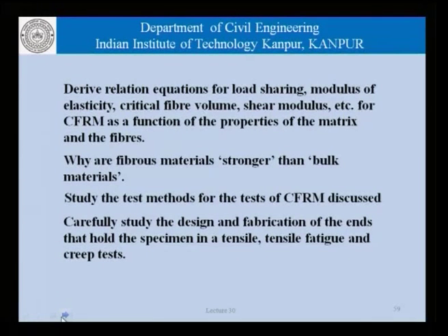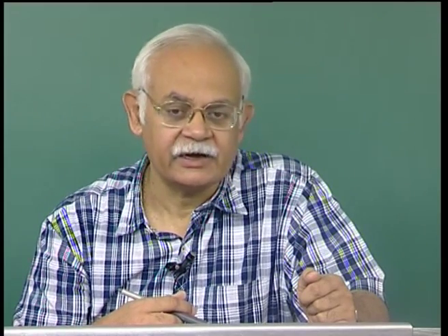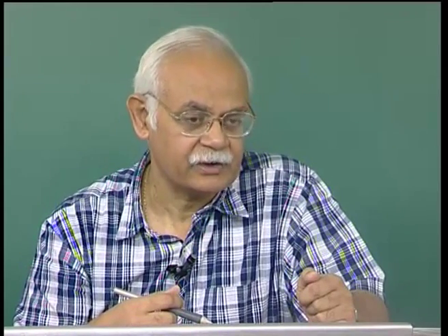We can study the design and fabrication of the ends or the chucks that hold the specimen in a tensile or a tensile fatigue or a creep test, so that we better understand the kind of discussion that we had as far as the importance of holding the specimen in place while applying the loads on the specimen is concerned. This is important because the stress levels are much higher than that of steel, and therefore, it is important that the chucks are designed and fabricated in an appropriate manner.